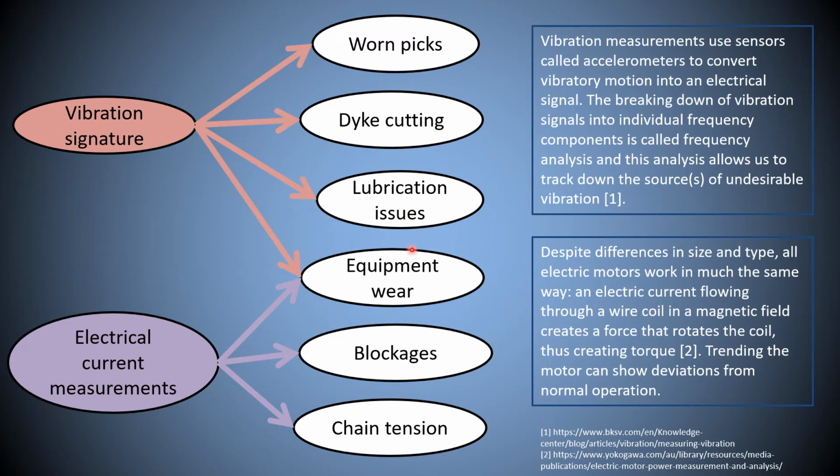So we're talking about bearings, bearing faults, and equipment wear, and look at, amongst other things, there's a lot of other issues too, but say as picks wear out on the shearer, pick that up in vibration, or as we're cutting through a dike consisting of rock that's much harder than coal, picking that up and allowing the machine to make a decision based on these conditions.